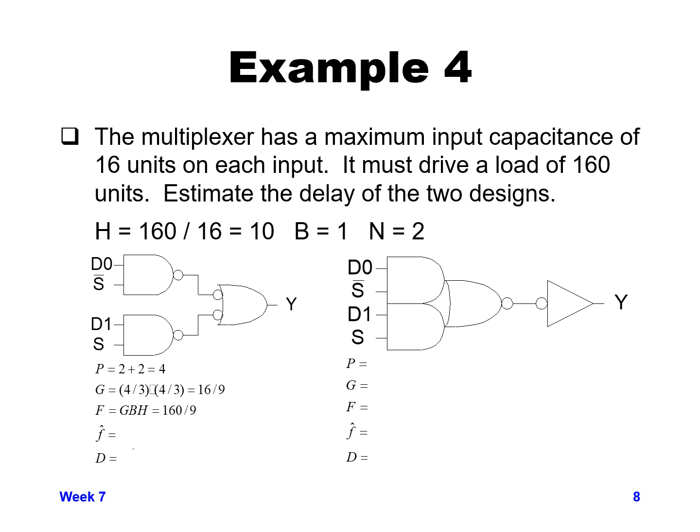And then the next variable is the minimum effort that we can have per stage. If you remember from last week, that is the capital F value to the 1 over capital N power, or the Nth root of F. So we have 160 over 9, we have 2 stages, so N is 2. We take the square root of 160 over 9, and we get the value 4.2.